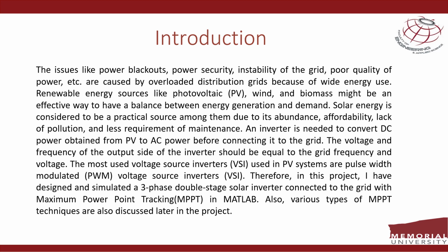The voltage and frequency of inverter output and grid should be similar. Therefore, in this project, I have designed and simulated three-phase double-stage grid-connected PV inverter with MPPT system in MATLAB. The different types of MPPT techniques are also discussed in the later part of the project.